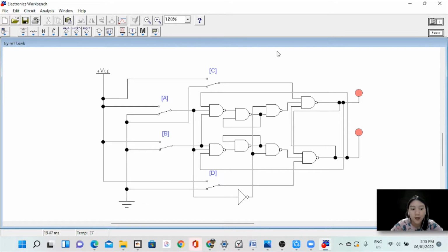So back to our circuit simulation of the T flip-flop, we have here our inputs, which were the shorted J and K terminals before, but now are replaced by the T terminal. Our Q and Q bar outputs, the T terminal, and our clock, pulsating clock terminal.